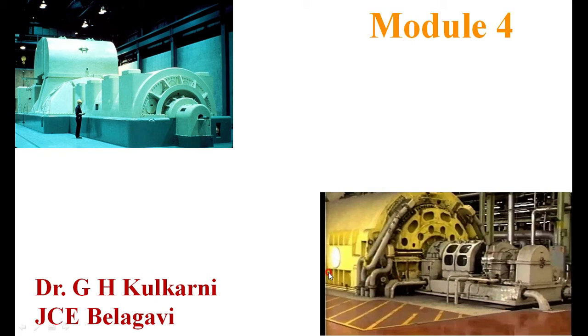Method of determining the voltage regulation of the alternator. We know that in the case of the synchronous reactance method, in finding the voltage regulation, we are converting all MMFs into EMFs.